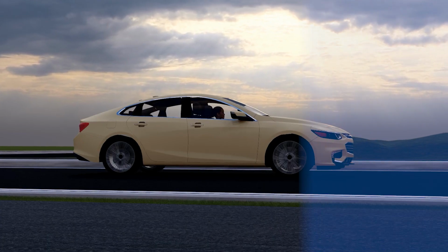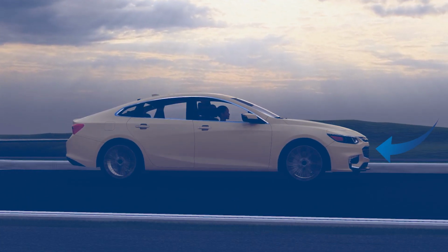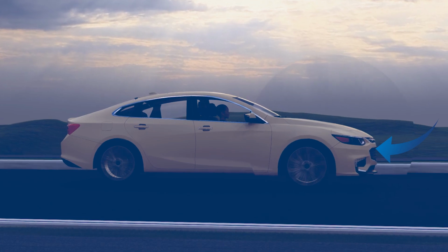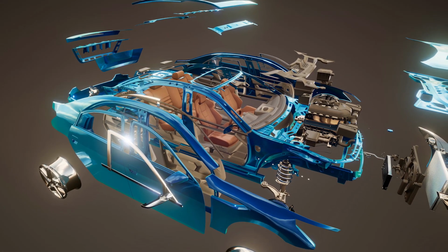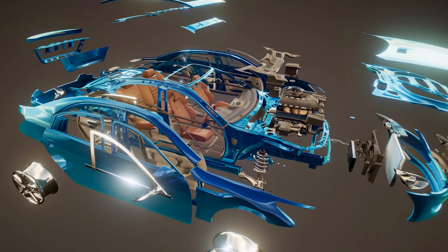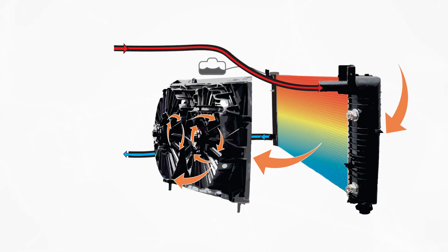The radiator cooling fan pulls ambient air through the radiator and circulates it towards the condenser and engine. When the vehicle is moving, ambient air entering from the front of the vehicle aids in heat transfer. If the engine overheats while in idle, there is likely a cooling fan failure that has reduced heat transfer.